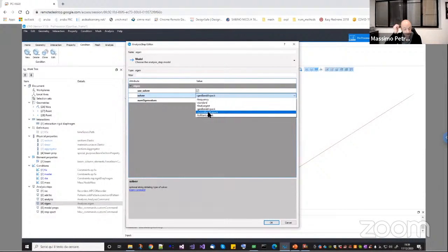So as long as you're using nodal masses, it is fine. But if you use consistent mass matrices, for example, with the displacement-based beam column or with the solid elements, the mass matrix is not diagonal anymore. So even if they're written symmetric, they actually meant diagonal. Okay, there is a typo in the name of the solver. But if the matrix is not diagonal, the symmetric band LAPACK is not working. So basically, you have two choices: the band ARPACK or the full Gen LAPACK.